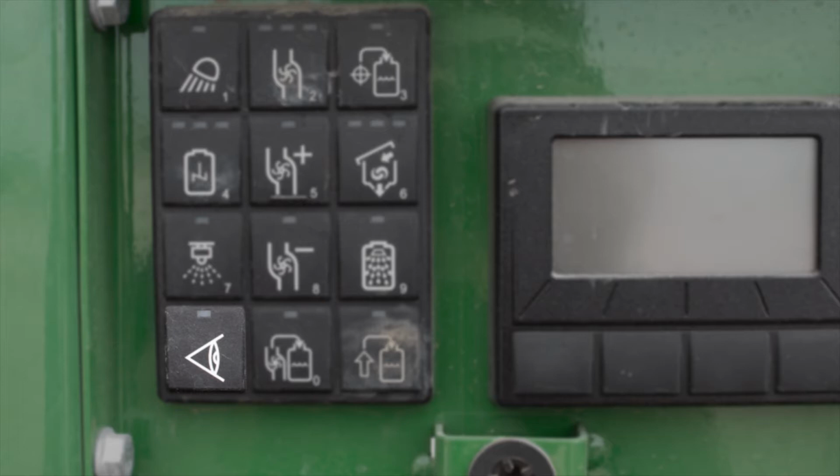So as you're out there, you got the pump running, you've engaged it, you got your booms unfolded, you can actually push that lower left button, kind of looks like a little eye, and it'll actually start a nozzle check. Now when you push the button, it's going to be delayed about 10 seconds to give you time to walk around behind the machine, and starting in the far left, it's going to turn on each valve section independently for a few seconds, so you can take a look at that, make sure you don't have a plugged nozzle, all your patterns look good, and then walk up and down the boom to make sure everything looks acceptable as the operator. So nice to be able to do that right from the ground.